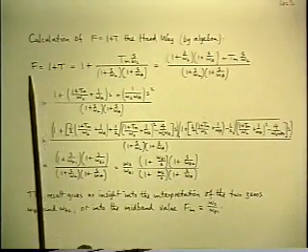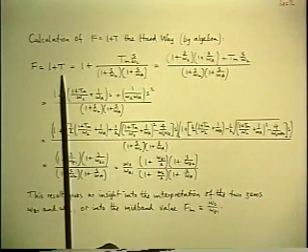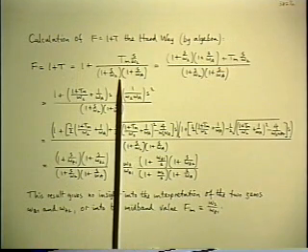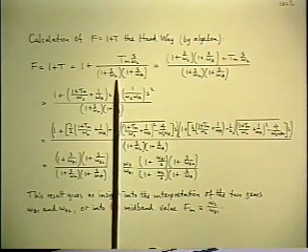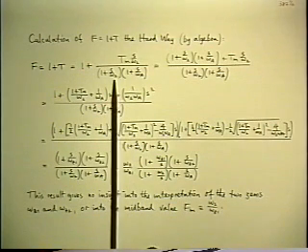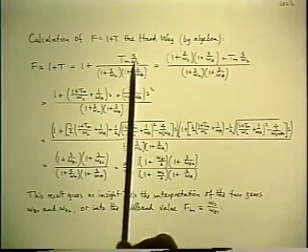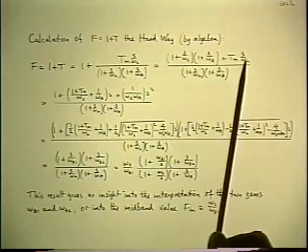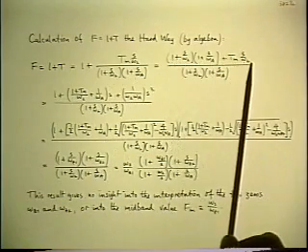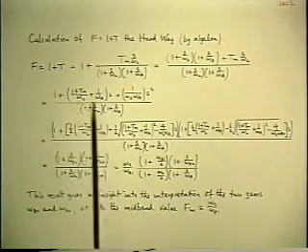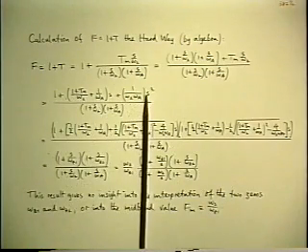So here's the process. F is 1 plus T. So you substitute for the T that we have already. And the first thing you have to do is that since we had T with the form of the inverted pole at omega 2, the first thing you have to do is put it back into normal format with an s term on top. Then you have to cross multiply. Then you multiply out the factors in the numerator because there's an addition to do. And you collect the terms and you find that you have a new quadratic equation.